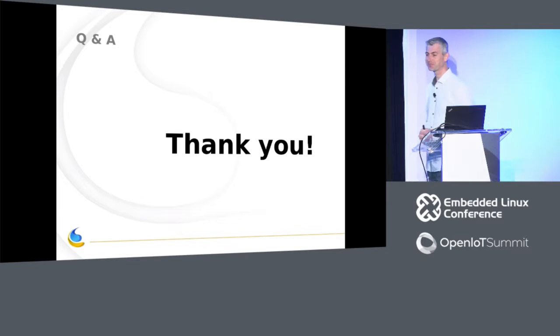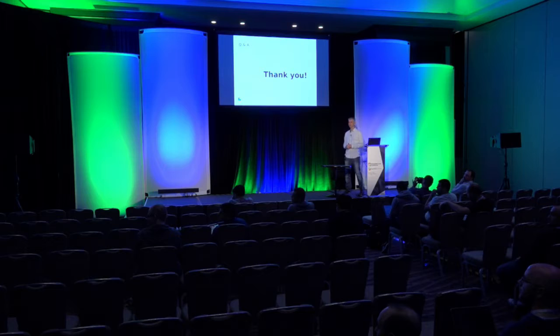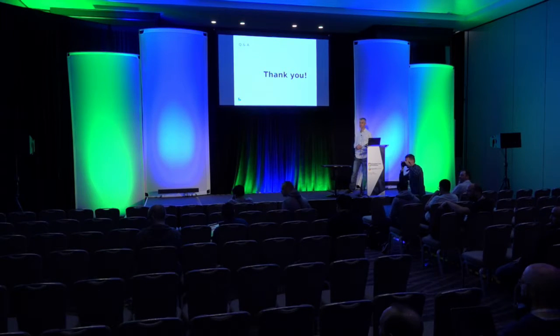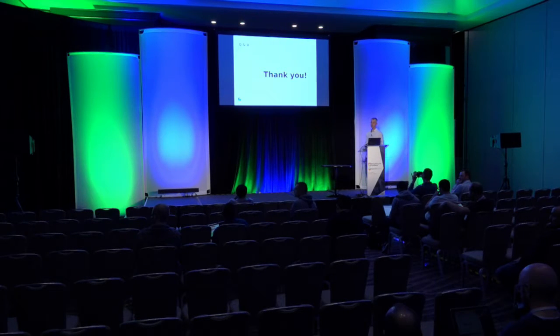Yes, Paul. So what percentage of the power management algorithms implementation are in the AP in the Linux kernel as compared to what's in, say, the microcontrollers that are running? So all the intelligence is on the AP. I have addressed only the UniPro switch power management, which is purely handled by the SVC. The module firmware does not implement anything. It's a slave to the AP.